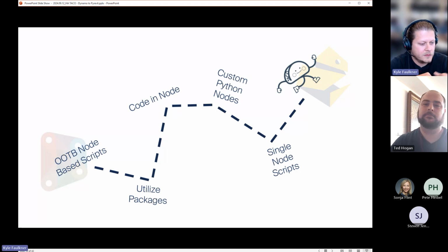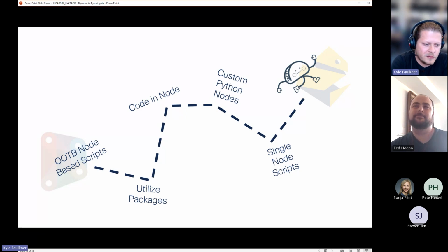And so you find some packages to supplement the out of the box nodes. I know when I was using Dynamo, I think Spring nodes and Clockwork, right? The huge ones. I don't know if they're still around, but some of those big packages were just supplementing the out of the box Revit nodes that maybe they should have had at the beginning, just to facilitate more complex scripts.